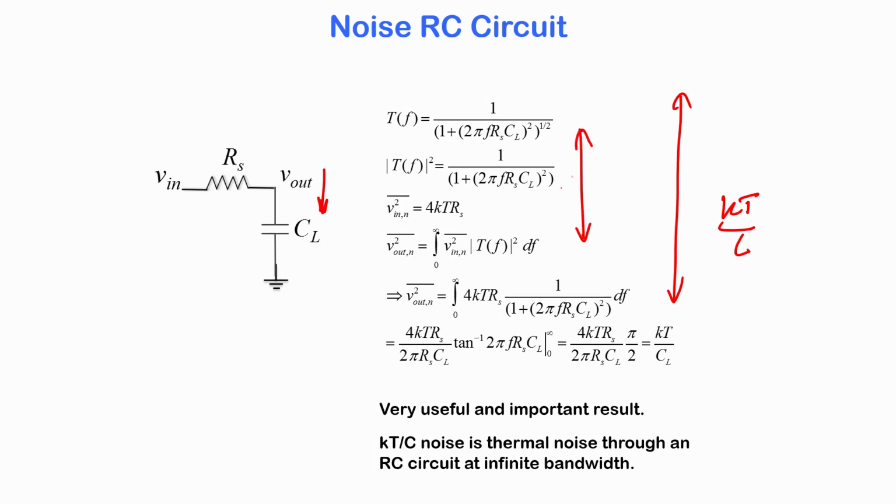It requires an understanding of certain formulas, and therefore I will not quiz you or examine you on this point, but nevertheless I felt it is useful enough to put down on a slide and leave it here. Okay, and this noise is typically just kT by C, it is independent of the resistor, and therefore if you are using a MOSFET as a switch, this is something that you can be aware of. So, with this we will complete noise in circuits, we complete our discussions on circuits itself, and we in fact complete our discussion on the crystalline semiconductor physics part of the course.